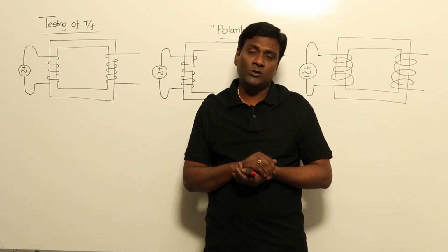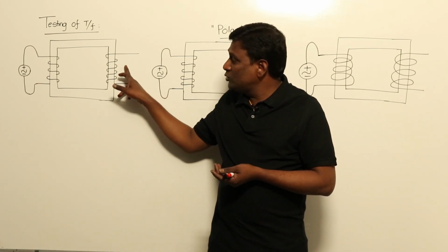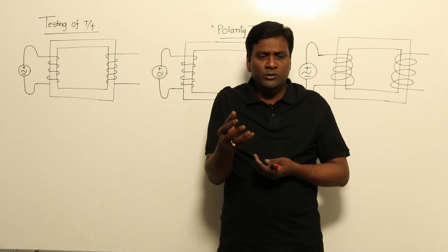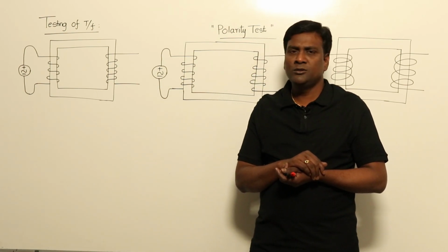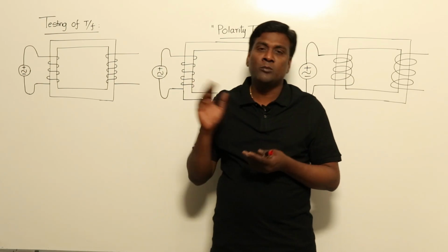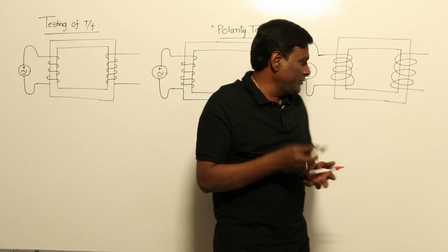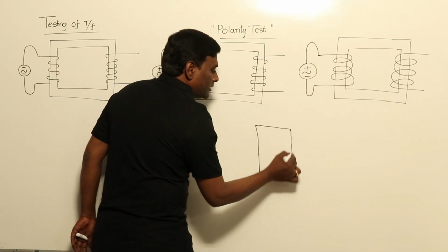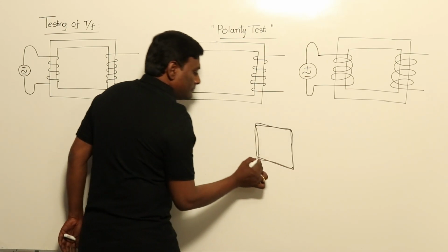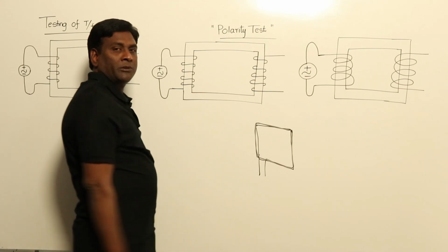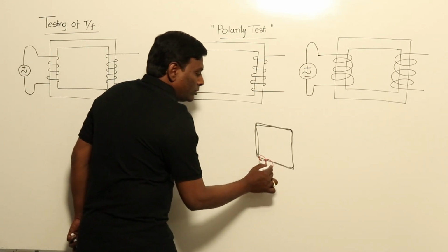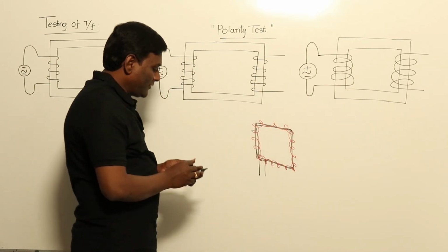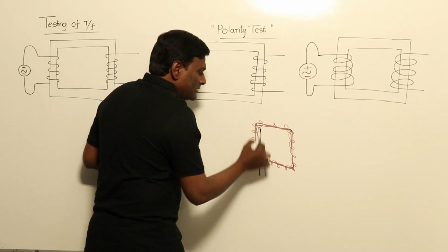Because in electrical machines, is it possible to find the sense of the winding for a practical machine? No. Is it possible to find the number of turns in primary or secondary in a practical machine? No. Basically, windings are preformed first. First the windings will be formed, immediately after that we are going to tape it, and after that we are going to provide some insulation here.